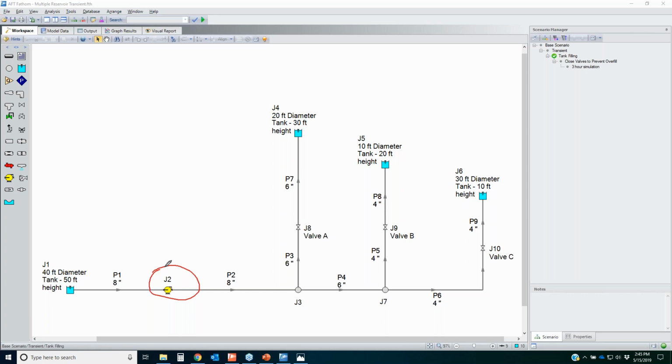And the reason for that is because oftentimes there is not a unique system curve that could even be generated, such as in this application. Since all of these are finite tanks and they're filling up during my transient simulation, the system curve would actually change.